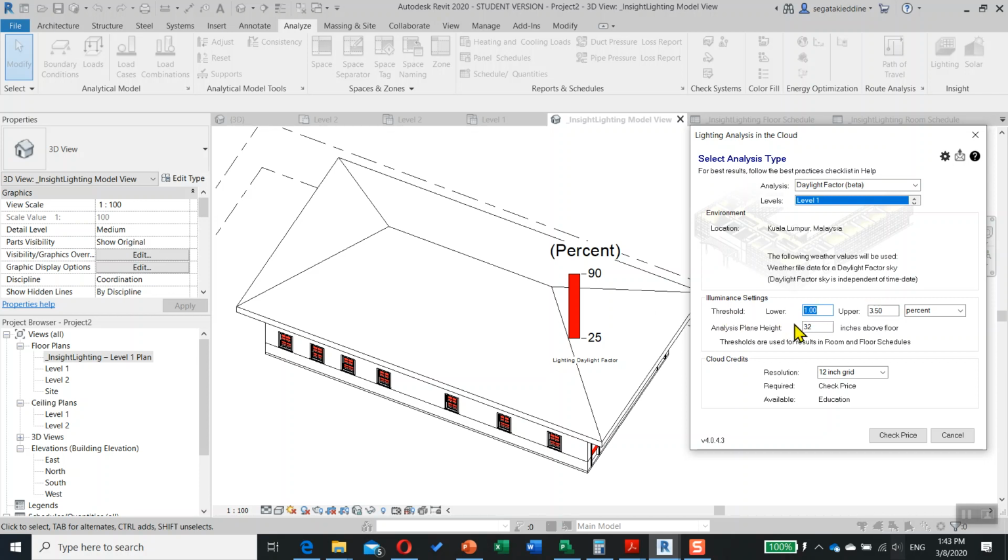It's very important, because it's not enough to see only colors. The daylighting factor is this number, and this is in this number, so you cannot take a decision. But when the standard tells you to calculate the percentage and it should fall between these two ranges, it will be easy to check. Here is the floor plan and the working plane height, so we keep that number in inches. Careful, it's in inches, so you just keep it.